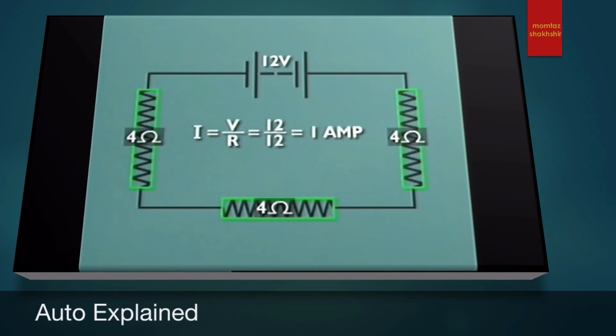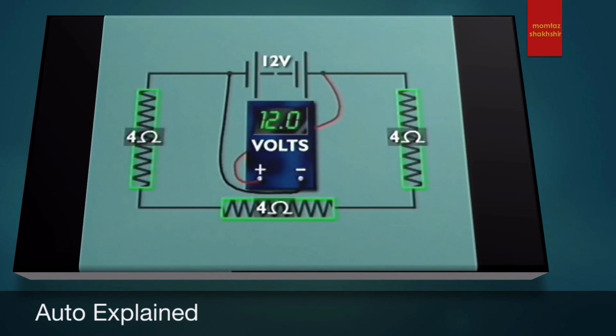However, voltage at different points changes as the electromotive force or pressure drops from a potential difference of 12 volts as it leaves the battery to virtually no difference, no voltage at all, as it returns. This is called voltage drop. It is caused by the pressure lost in driving the current through the resistor.